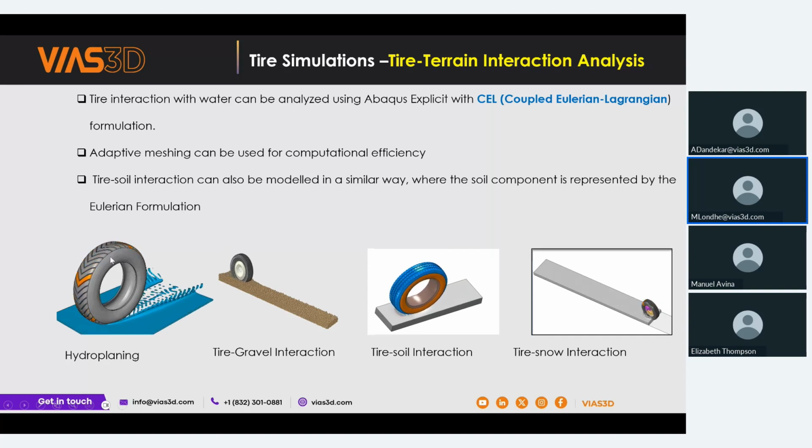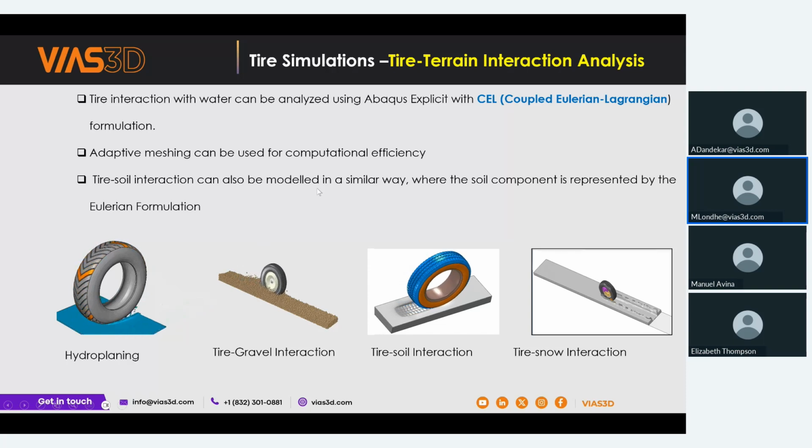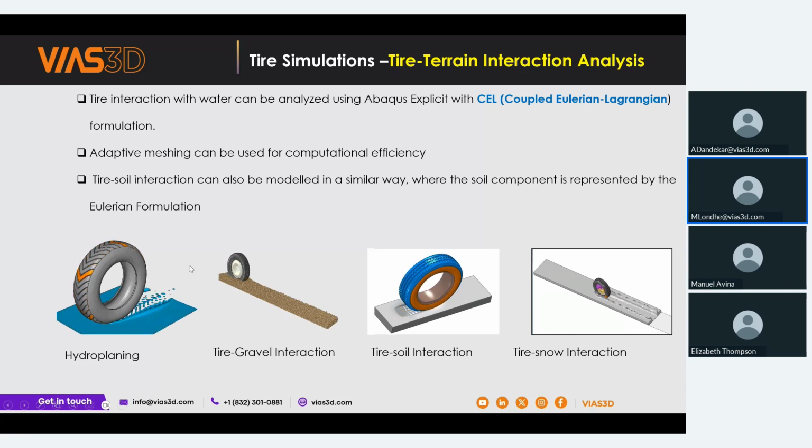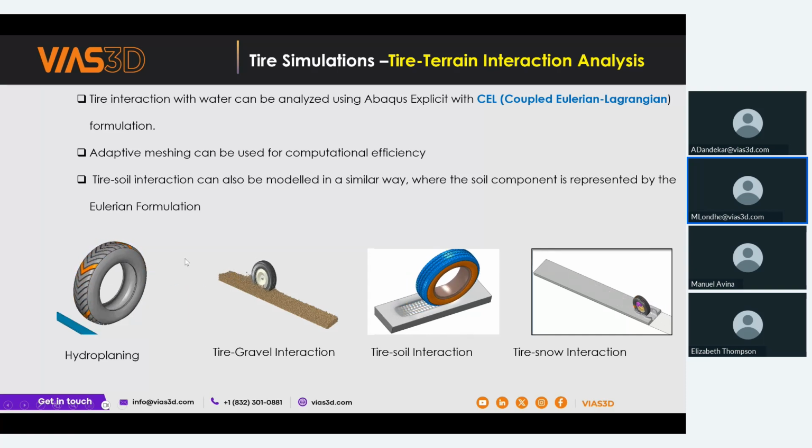This approach you use for the solid elements, while for the fluid elements you use the Eulerian mesh or Eulerian approach, where your mesh remains constant, and using the law of conservation of momentum, you calculate how your material is flowing.